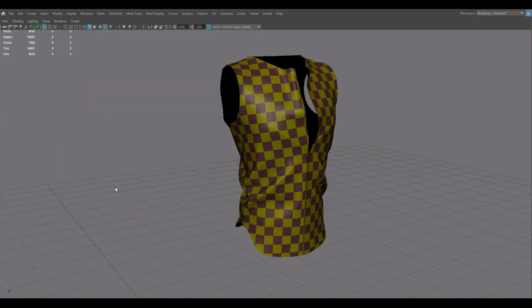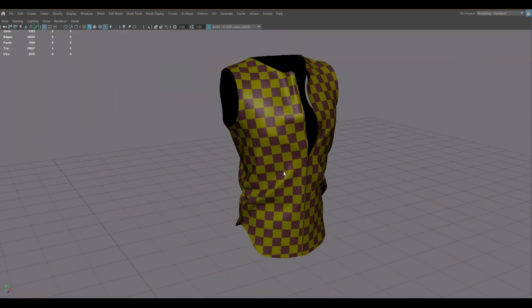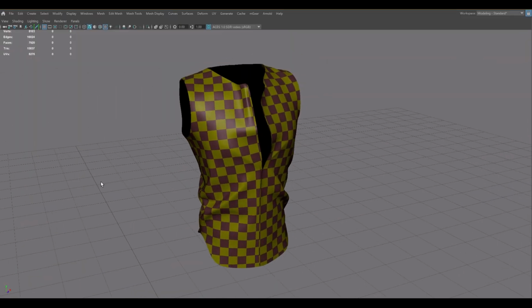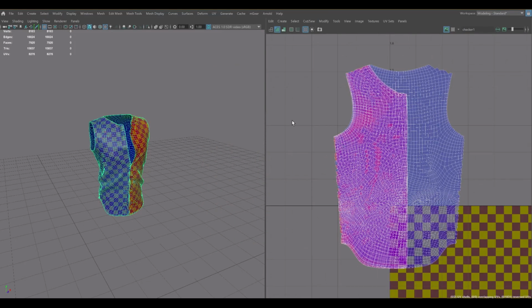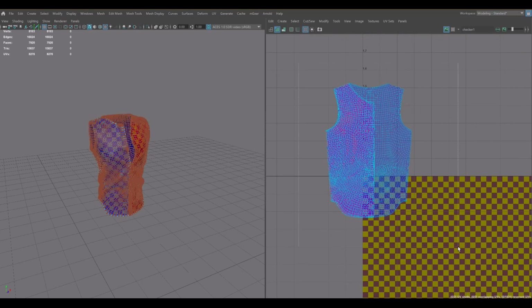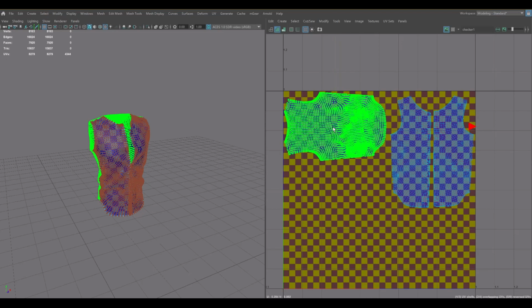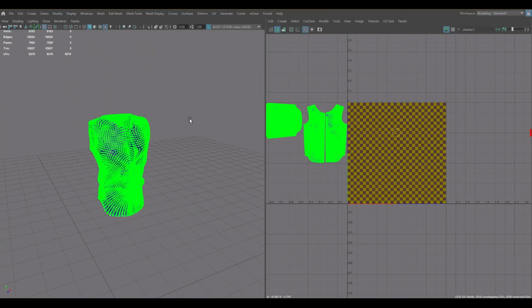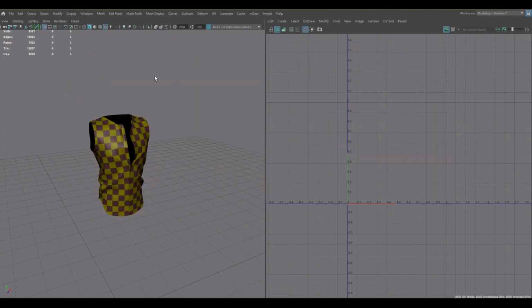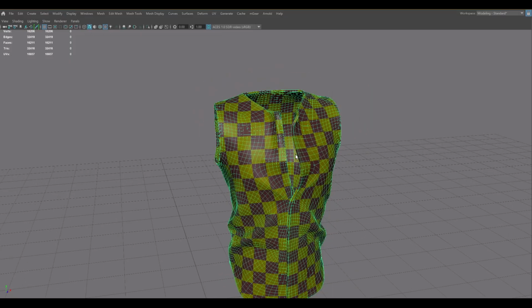Now, before we leave, the elephant in the room here is that you probably want some thickness on this mesh. And to do that, I'm going to use the extrude function, and I'll just do a quick UV layout, and I will shunt those off to the side, doing that so that they don't overlap when we extrude this puppy. So now we're going to go up to mesh and extrude, just reverse them back.